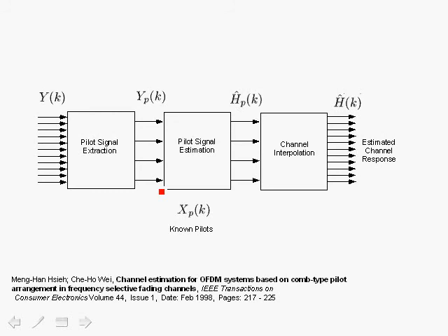frequency response of the channel at the pilot locations, then we can perform a channel interpolation and then find out an approximation to the channel frequency response at each data carrier location, and then we can use that to equalize the channel on a per carrier basis.